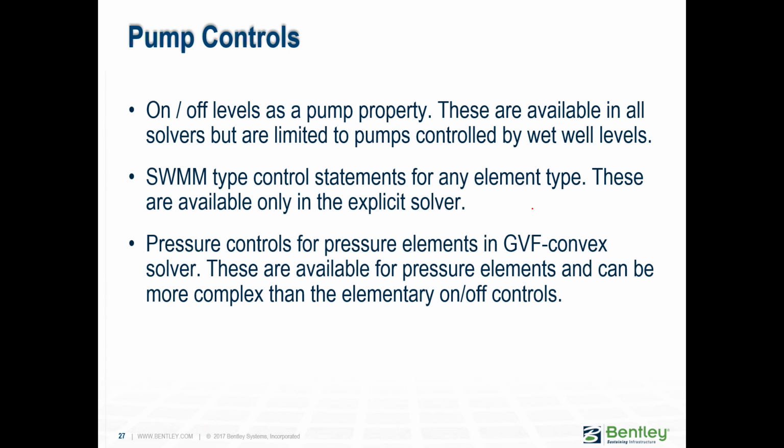Okay, so with any of those types of pump inputs that you've decided to use, you got your pump curve. Now what? Now you need to tell the software what triggers a pump to go on or off. The controls are a little bit different again in the GVF-Convex solver. If you want to time it, say it goes on at 6 a.m., off at 10 a.m., etc., or the trigger is maybe the flow in a pump, or you have unusual controls, then the GVF solver gives you more options.